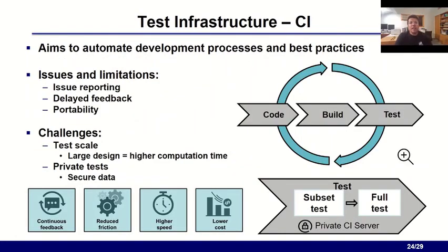Continuous integration is commonly accepted as a game changer that allows us to pinpoint broken code changes. It has been applied to many fields, and EDA tooling is benefiting in its turn from such infrastructure. This is another area which was not clearly enumerated in the original project task structure. By introducing the CI, it is possible to build and test the tools individually, and if successful, it tests the new code changes within the OpenROAD flow. This ensures that the OpenROAD unified build environment isn't compromised by the code changes.